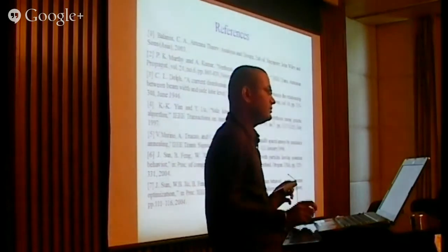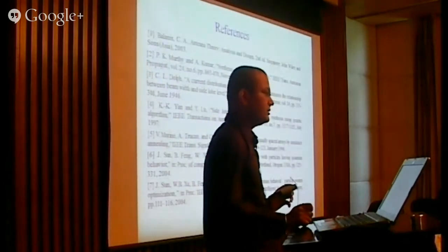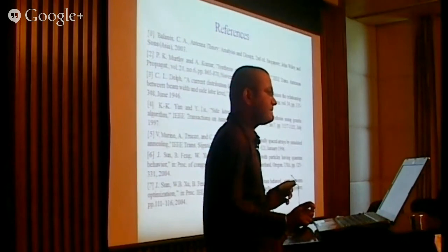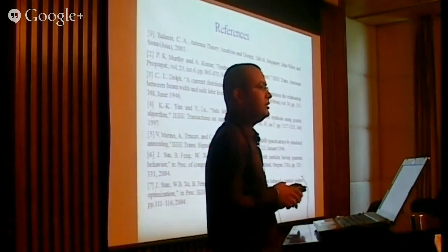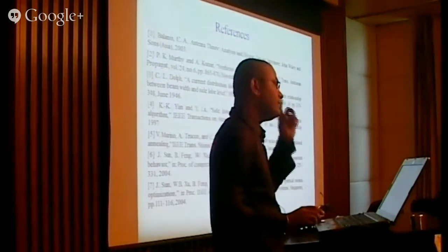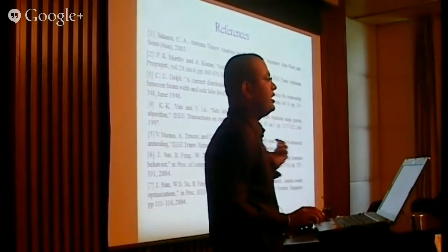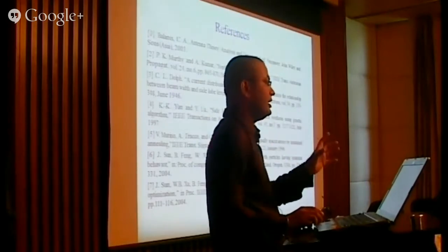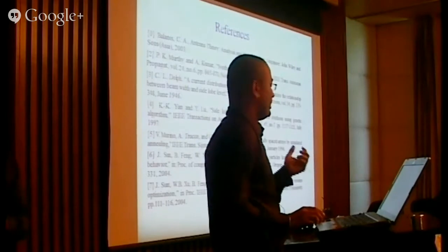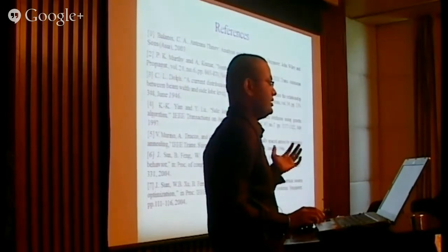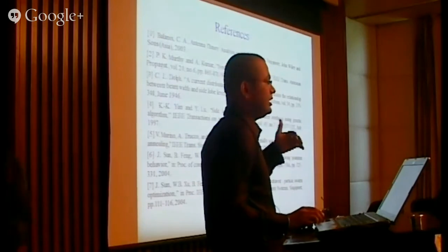There are other methods of synthesis also, in which the desired side lobe level can be achieved. How do you justify your method in comparison with the existing synthesis methods? So here we find a suitable element spacing. Here we vary the element spacing, and we obtain the desired spacing. Here we want to reduce the side lobe level to minus 35 dB.